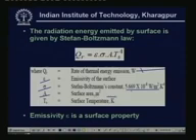Unlike the conduction and convection equations, the Stefan-Boltzmann law can be derived from basic thermodynamics. That means it is not based only on observation. And here the emissivity is a property of the surface, and if emissivity is 1, we have an ideal surface. For an ideal surface, the emissivity is 1, and such a surface is known as a black body. A black body has nothing to do with black color. A black body is an ideal emitter.